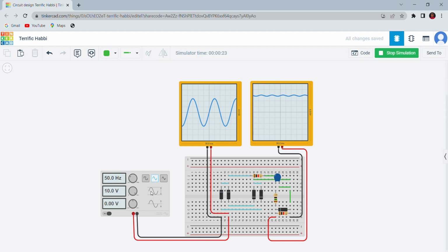Okay, I will continue explain about the current flow. So for the positive charge current, it will go through the diode 1 first because it is the forward bias, and will not go through the diode 3 because it is the reverse bias. Then the current will continue flow through the resistor and will not flow through the diode 2 because it was the reverse bias.